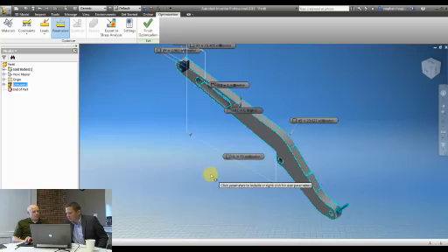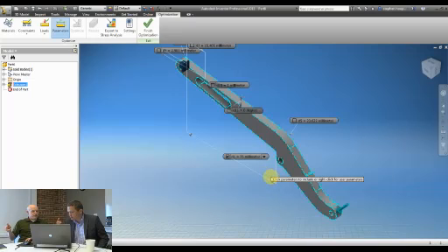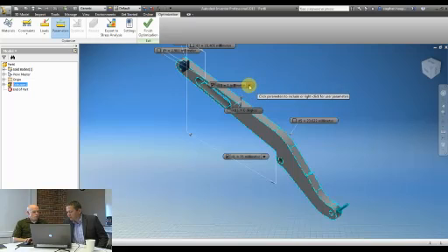So we can just select the model and it shows us all the parameters that are on the model, and I'm going to tell it that there's a range of different sizes I want to have a look at. So I want to see what would happen if we made that linkage 50mm. So if this entire arm was 50mm or 75, and you could put in a bunch of these, right? Yeah, exactly. I mean, it would be pretty easy to figure out just on my own those two values for the length.